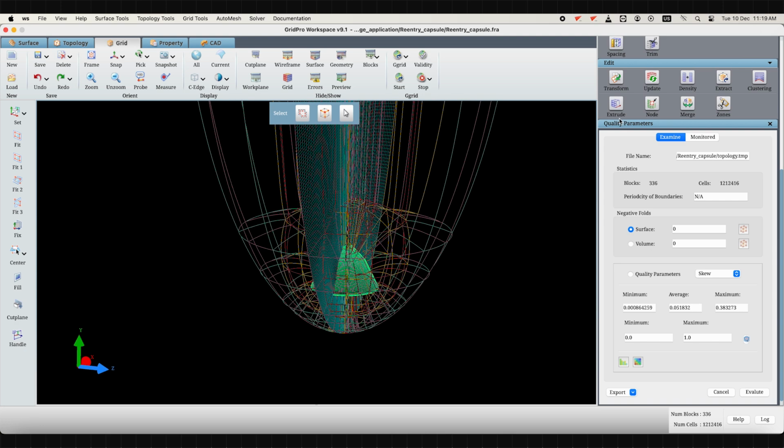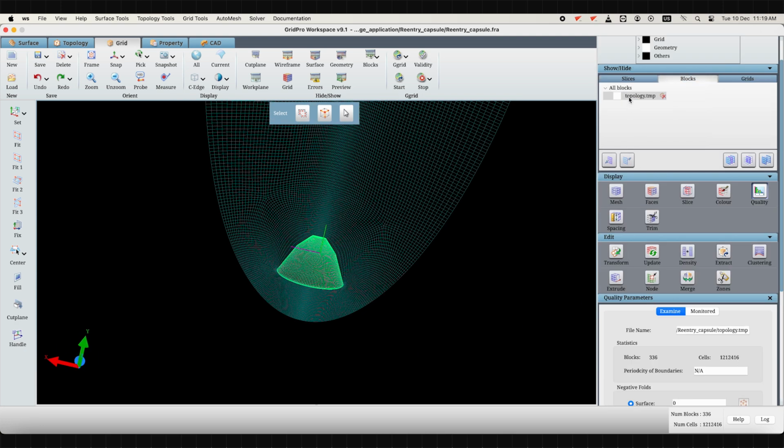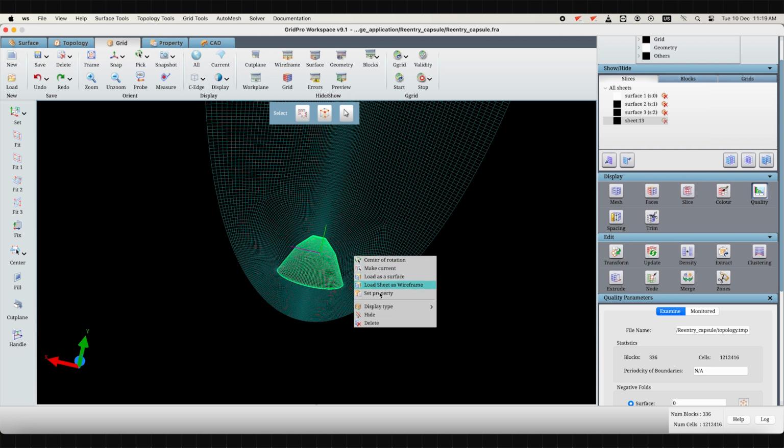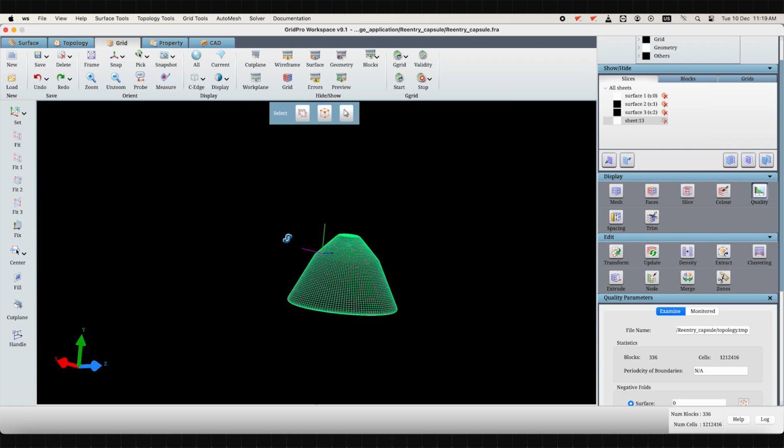The restart option, combined with surface replacement, offers a significant advantage for gridding parametric variations by drastically reducing grid smoothing time and enhancing efficiency. We hope this video helps you understand a way to save grid processing time for mesh generation of parametric geometry variations, maintaining self-similar and high-quality grids.